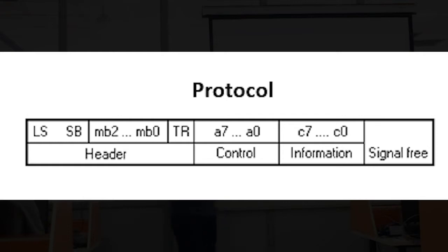And what this does is, based on how well it is received, the receiver is able to calibrate itself to the incoming signal, right? So the leader symbol is just for that. And then comes the start bit. The start bit is always a 1.